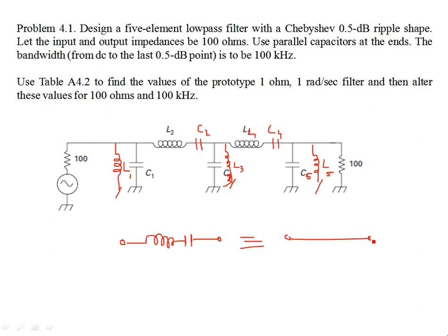It will be equivalent to a short circuit at the resonance frequency omega naught, which is determined purely by the reactive elements. This is LC, so at omega naught equal to 1 over the square root of LC, you're going to have a perfect short. That is, the transmission is going to be seamless, right? It's a short circuit, so you're going to have maximum power transfer, right?